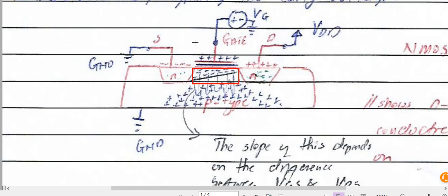So what is going to happen now when you apply a voltage here? The inversion layer which we talked about here is not going to remain the same. Because of the positivity on the side, the more VDD increases, the more positive it becomes, and it makes this side pinch. Because of the positivity here, it repels the electrons and pinches this layer over there. We need a specific voltage here, which is VTN, to have electrons flowing here.